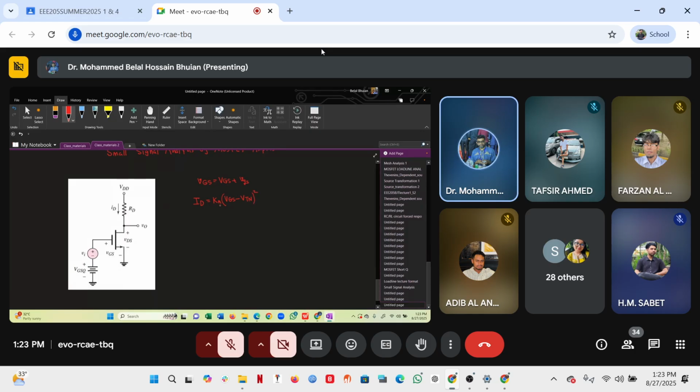That's for the MOSFET. Now, if you have both AC signal as well as DC signal present, the current that will be flowing is the instantaneous drain current, iD. So what will be the voltage? The instantaneous gate to source voltage. So iD can be written as Kn (vGS minus VTN) whole square. Okay, let's do a little bit of math.